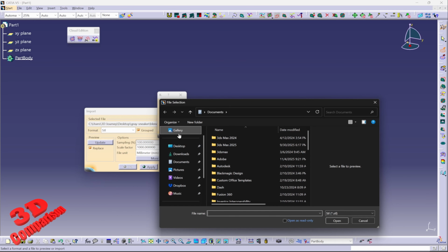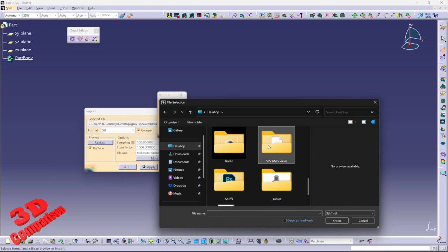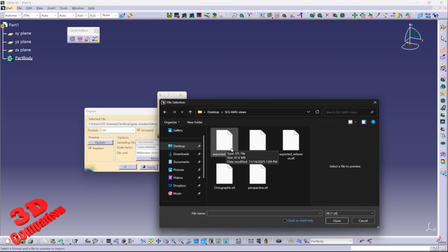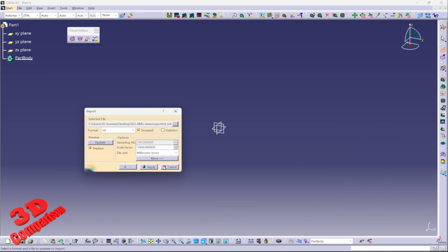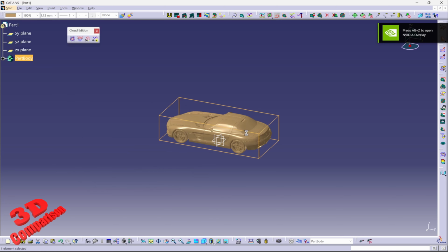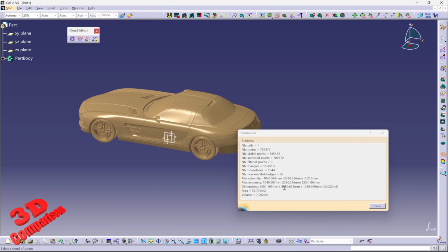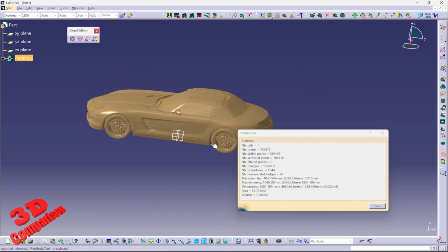And in this case, since I'm transporting those from Blender, which has meter as the default unit, I'm going to go over here, so exported reference. I'm going to hit apply. And I'm just going to check the overall size for this. We're going to see that in this case, this will have the correct length, so 4 meter 4.6 in this case.